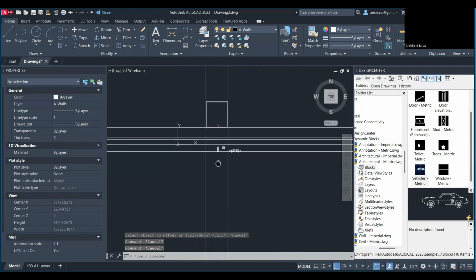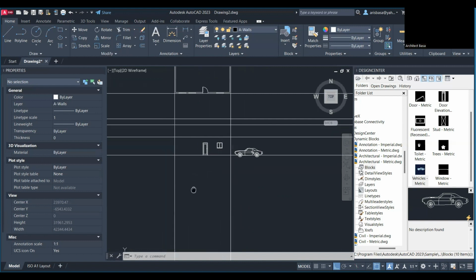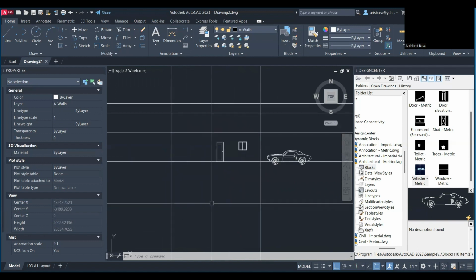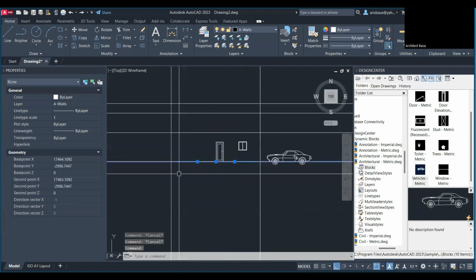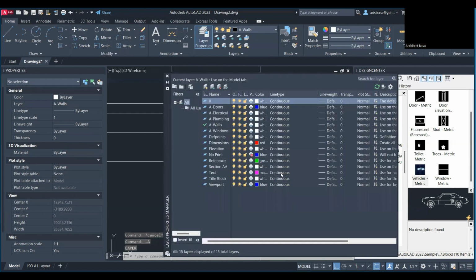Okay. So now, when you create an X line, it's not good to use white line because it is so visible, right? Because this serves like your reference line. So let's change the line color. Okay, and better put it in a correct layer. So let me just check the layer that I have right now. So the layers that you are seeing are based on the template. You're already having this, right? So for now, we haven't placed the objects into their correct layer.